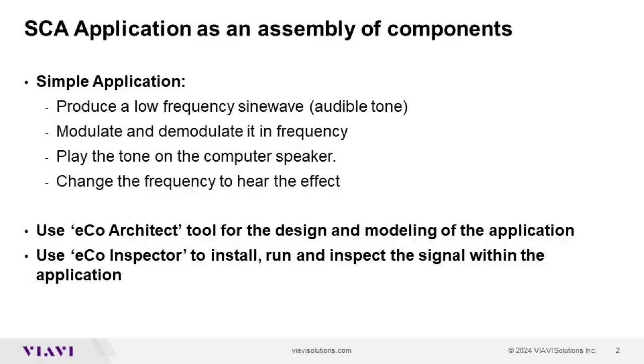To make it simple, the application we will be developing will produce a low-frequency sine wave or an audible tone. We will modulate it in frequency and then demodulate it to play the tone on the computer speaker. We will show by analyzing the signal constellation that the sine wave has really been frequency modulated. Pretty simple, but it will quickly show the main concept for the development of applications as an assembly of components.